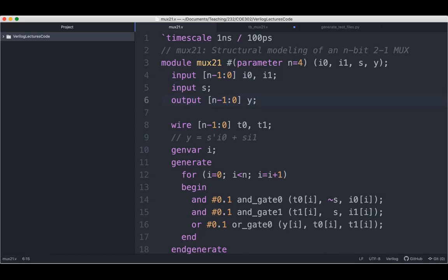Now there is an implicit keyword here that is omitted. It's called wire, and this is the keyword here. We say input wire, then you give it the width, and also output wire, then you give it the width. If you don't mention the data type, it is by default a wire. The other data types are registers, and we also have other types, but most likely in this course you are going to work with either wire or register. Similarly for S, you have input wire S.